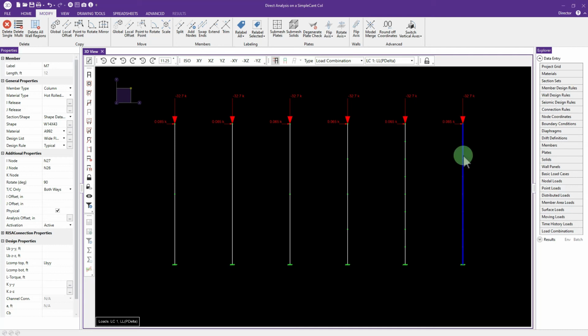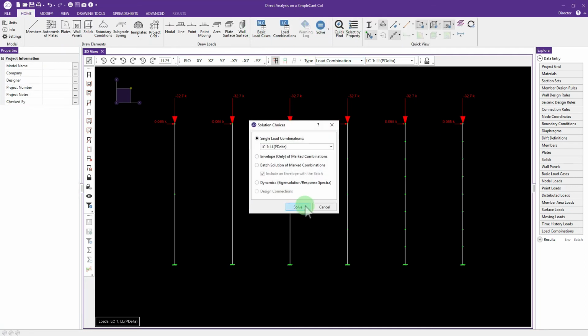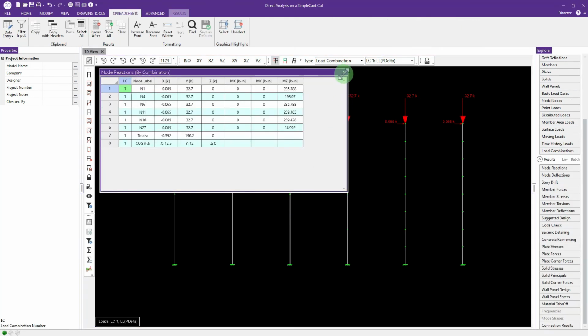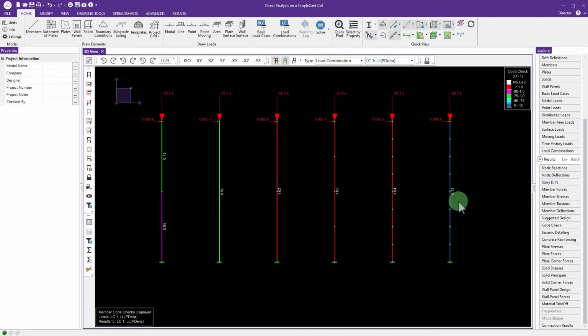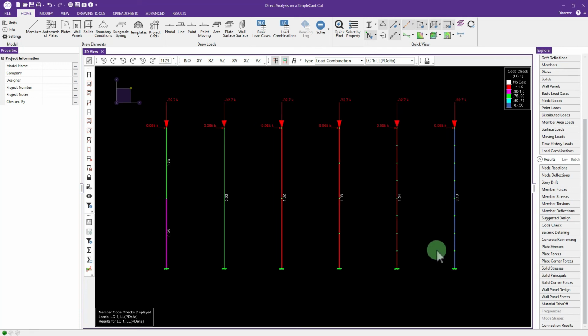Everything else being equal, run the analysis. And go ahead and pull up our, of course we already discussed the bending and all that stuff. That's not going to be any good new information, so I'll check the unity here. Now I have a column that's 13% stress. Is something that works very well. You might want to use this column for this section if you had these loads on it.